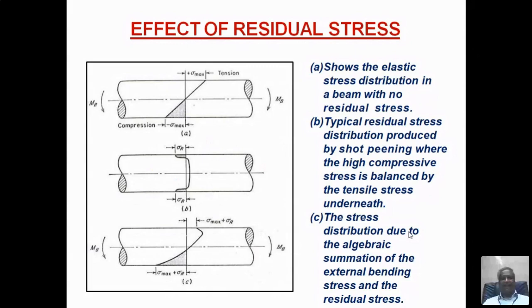Is there any method or technique to evaluate the results? There are many methods. There are destructive methods and non-destructive methods. For destructive methods, there is a method called the deep hole drilling method. They work on the strain gauge principle. And non-destructively, you can evaluate. The best method is the non-destructive method. You can use XRD, this is X-ray diffraction, radiography method. There are a lot of goniometers available. So even in Tamil Nadu, I think many places have it.